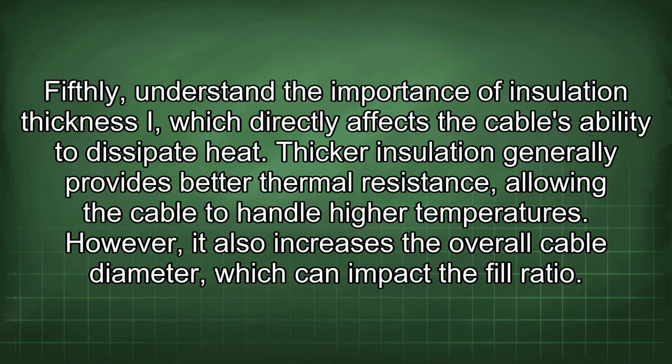Fifthly, understand the importance of insulation thickness I, which directly affects the cable's ability to dissipate heat. Thicker insulation generally provides better thermal resistance, allowing the cable to handle higher temperatures. However, it also increases the overall cable diameter, which can impact the fill ratio.